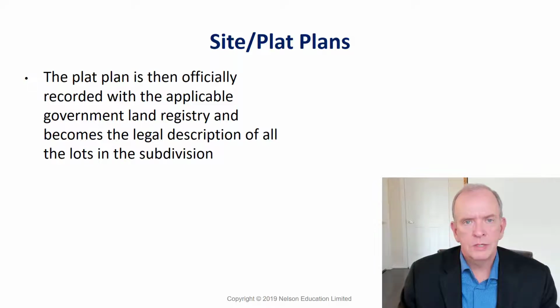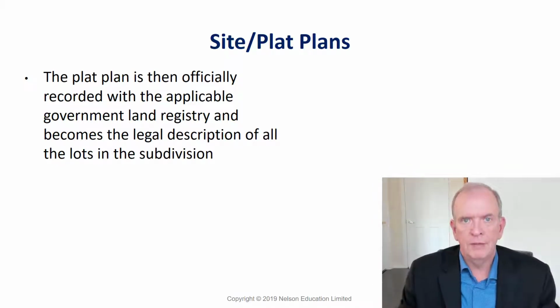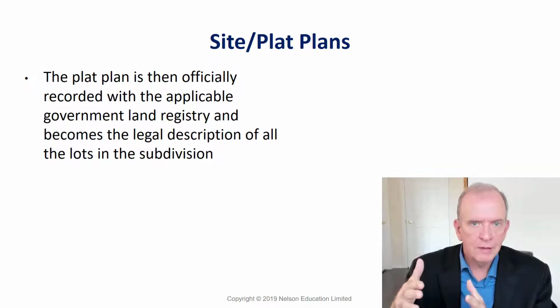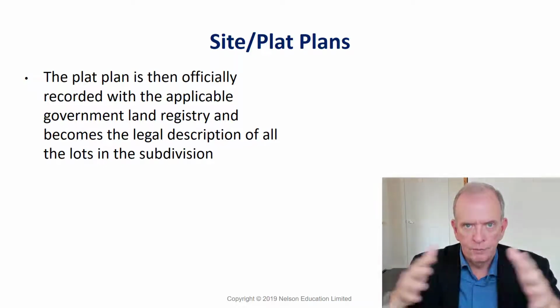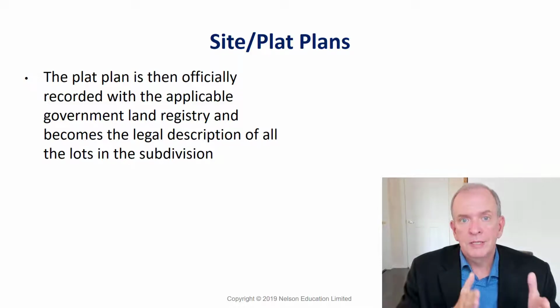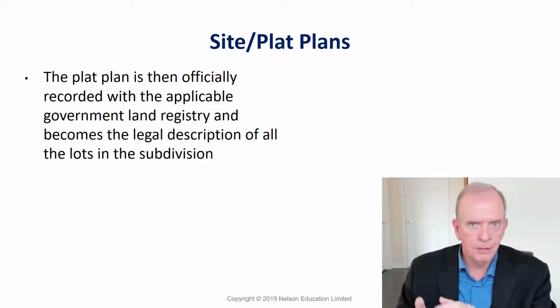And different municipalities will have different names for it. They may call it the draft plan the builder submits for that particular area in that plat plan. They can't really sell any units until they have draft plan approval from the municipality. So that's the aspect of the development of that area. And of course, if you do get that approval, you're going to subdivide the lots from that overall lot that maybe the builder purchased from a farmer or something of that nature. It's going to be subdivided, and there's going to be a legal description for each lot so that they can sell each lot separately.